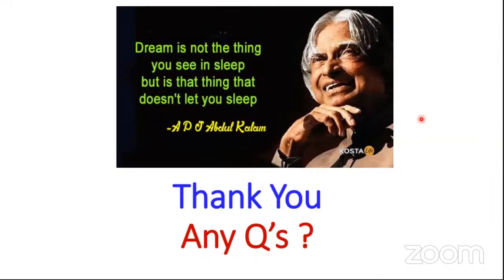Is this process cost efficient and environmental friendly? Okay, on cost effectiveness, as we have seen, as far as the complexity of the part that we want to print compared with conventional manufacturing techniques, yes, it is cost effective. And when the quantity of the part to be produced is less, obviously the conventional manufacturing process will have very high cost compared to the AM route. So given these two conditions, AM technology is cost effective.